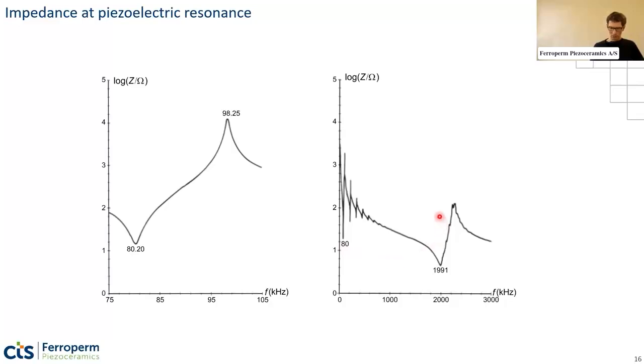That disc is also 1 millimeter thick, so that thickness will give another resonance, a thickness resonance, which is here close to 2 megahertz. So you see 2 distinct resonances here, and then also some other smaller ones, and these are the harmonics, the overtones, and I mentioned the lambda 1 and lambda 3. This one is equivalent to lambda 3, basically 3 half wavelengths inside the solid part over the diameter of the part. And this is then lambda 5, 7, 9, 11, and so on.